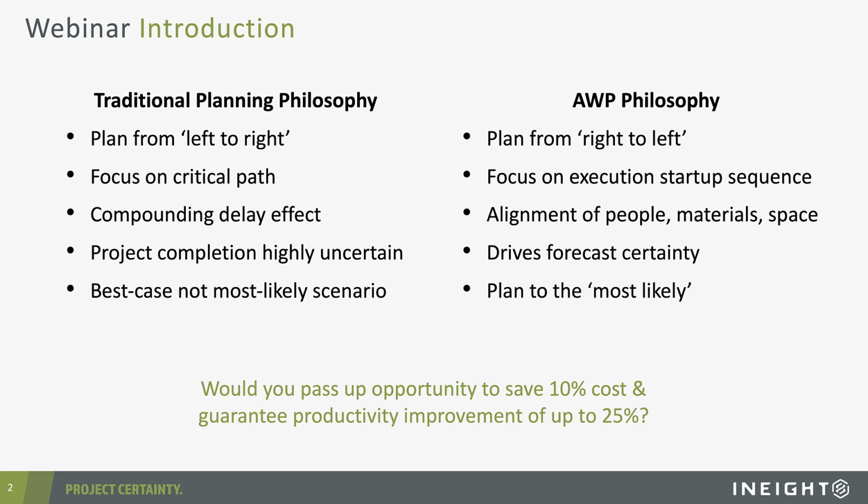And again, I think historically, we focused on what we call the critical path, the work elements that don't have any float, such that for every day that they are late, they have literally a one-for-one knock-on effect per day on the project completion date.